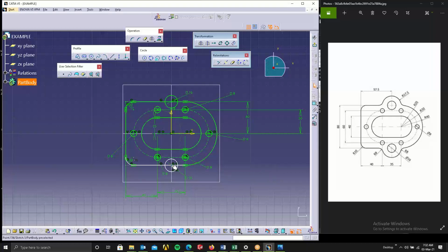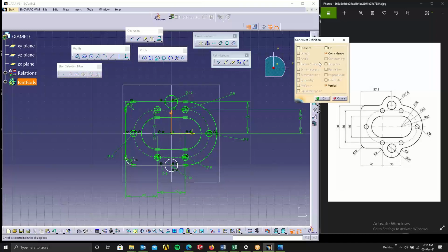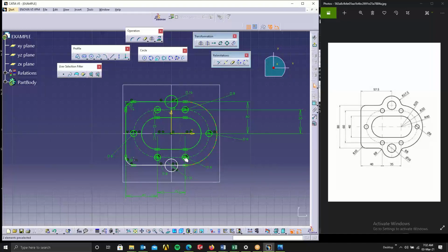This thing is not constrained. That means the point is not tangent with this. So when it is tangent with this, why is it not constrained? Because this line is not tangent with it. So why is the line not constrained? Because there is no height we have specified. So just give a proper height and it will become constrained. I can notice your problem.